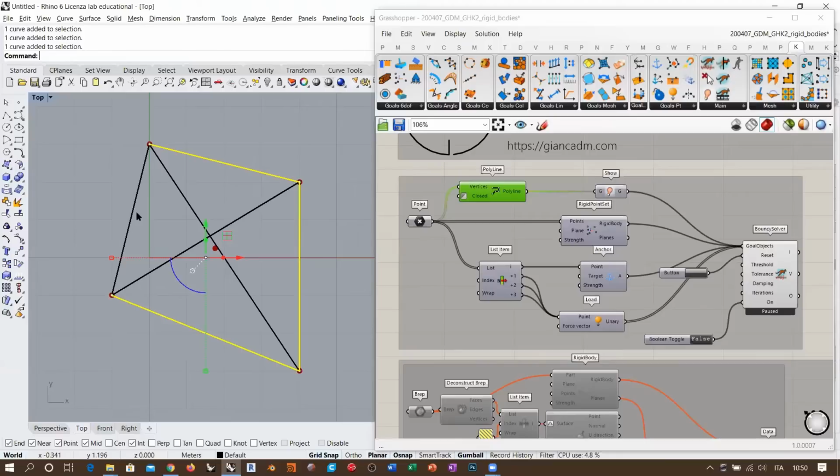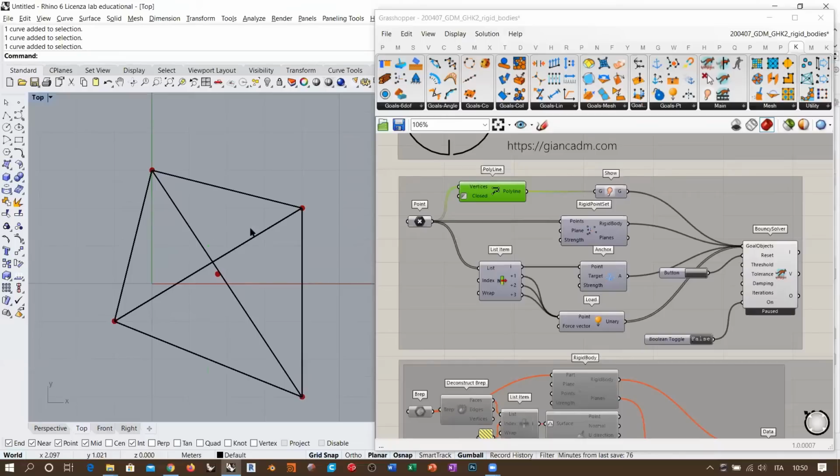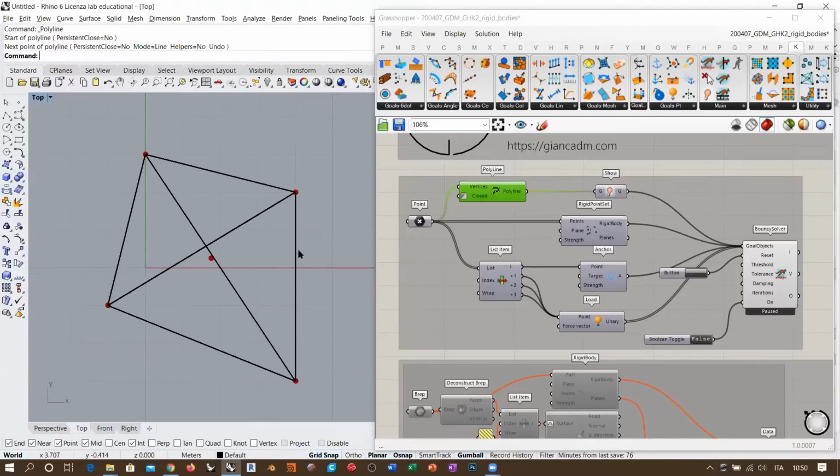So for example, if we don't consider the diagonals and we consider the four sides of this rigid structure, this thing can shear basically. So for example, there is no anchor or restraint that will be avoiding this point from sliding in this direction, and then this quad here will compress in the cross direction.